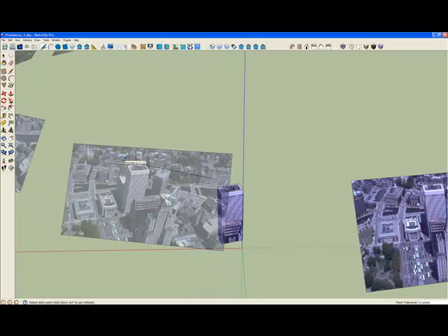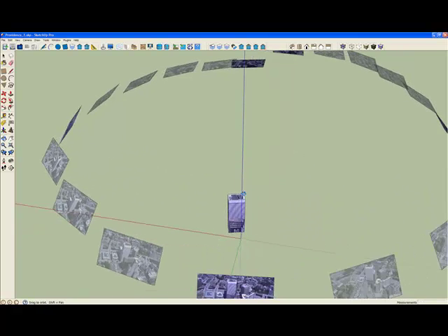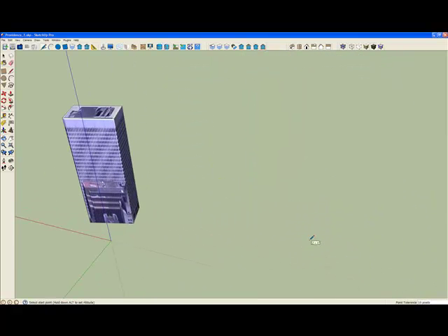So for example, the inferencing will be relative to lines and arcs, so you don't necessarily have to be constructing geometry from the aux views. We can just construct it on the XY plane as normal SketchUp tools. If I construct a line, then the next edge is perpendicular to it. It's highlighted and the tooltip tells me that it's perpendicular to the previous edge.